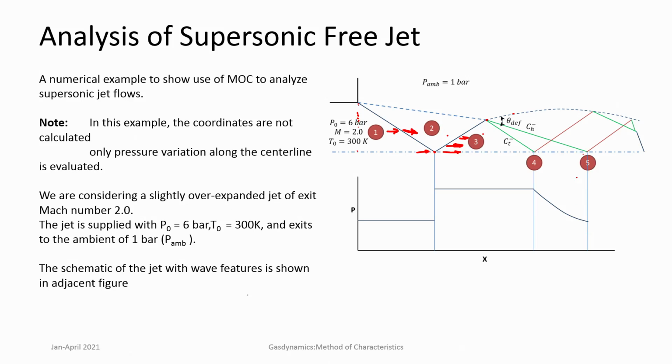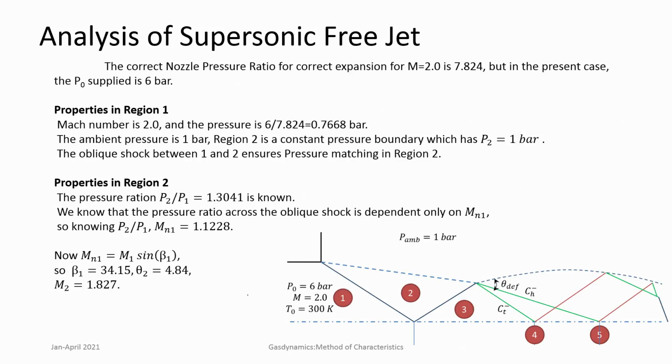So, this analysis can be carried out using the method of characteristics and shock waves together. Those shock waves are discontinuities. So, across the shock wave there is an entropy jump, but once you get into uniform regions they are isentropic. So, those regions can still be analyzed using MOC. At the shock you will have to apply the shock jump conditions.